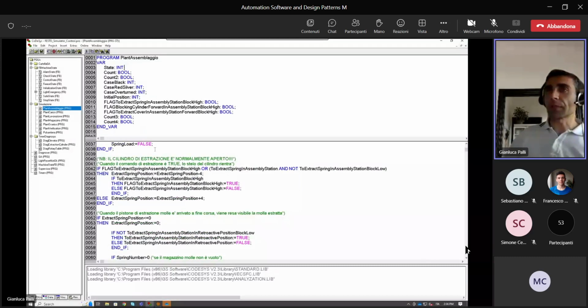The visualization is a bit different because, let's say, Codesys is more compliant to the standard, and so it shows the variables on top and the code in this middle window. While in Automation Studio, you see, the variables are stored in a separate file. So in this sense, every manufacturer has its own implementation of the standard. Let me say that the standard here is much more clear.